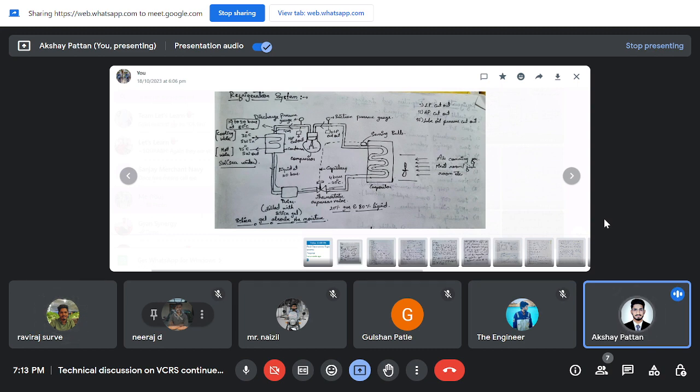So basically, why is high pressure taking place? Because there might be some dust particles stuck inside the flow. That's why the flow of refrigerant is not proper, causing the high pressure. And there might be improper lubrication and friction inside the crankcase of the compressor. Due to the wear and tear, the temperature increases, and as you all know, as the temperature increases, the pressure also increases, right? Am I right or wrong?